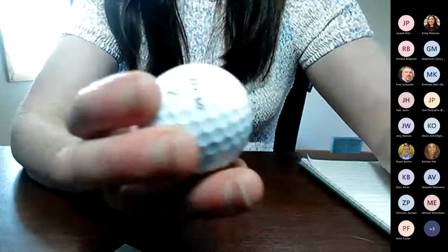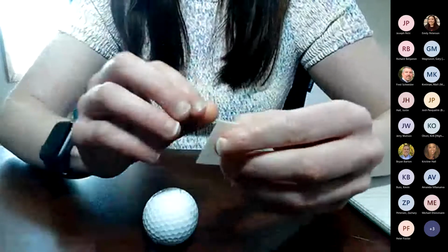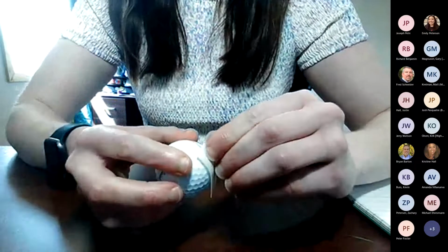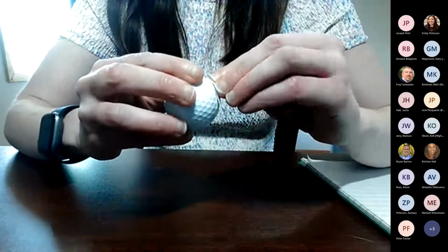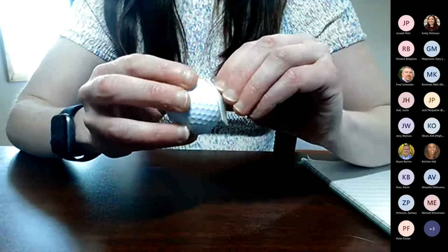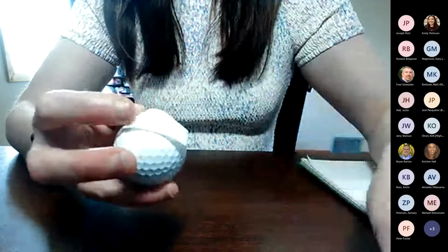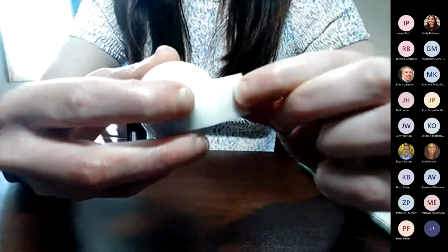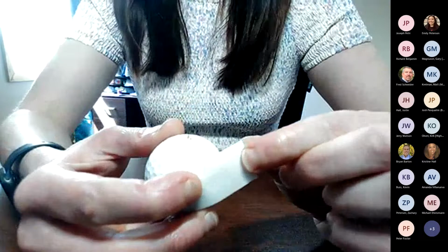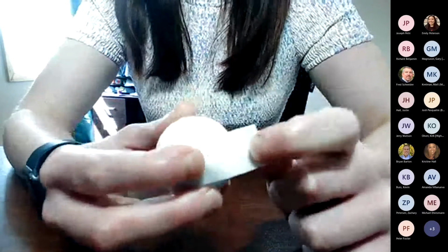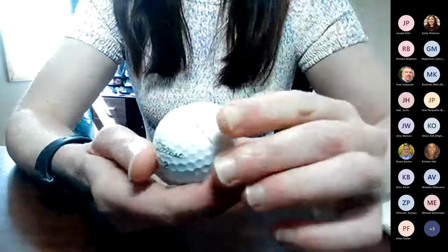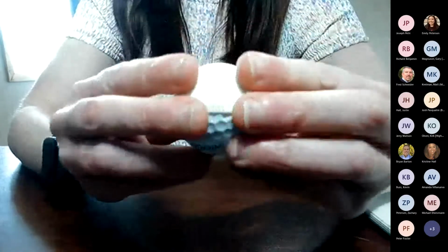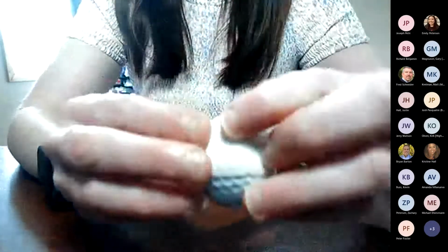So now a different tape that we have that is also a go-to product is 8926. This has 1.5 watts per meter Kelvin, a little bit higher than the 8800 series. What's also a little different from the 8800 is that it doesn't have that viscoelasticity. What this is really popular for is LED lighting applications, where they're so hot and they're larger now. They need to dissipate that heat, so they'll use something like the 8926 to dissipate a higher amount of heat.